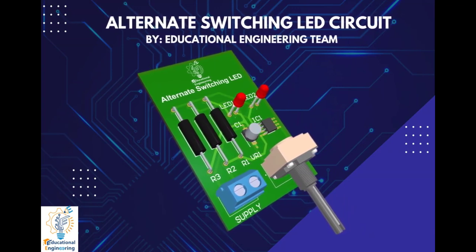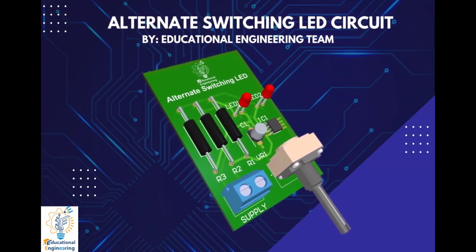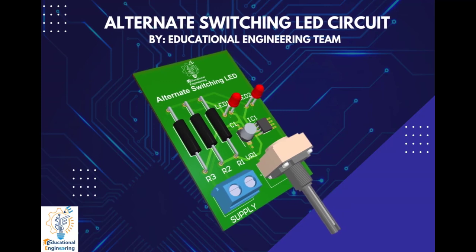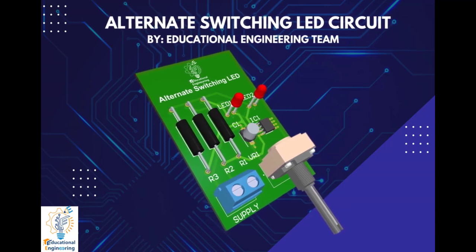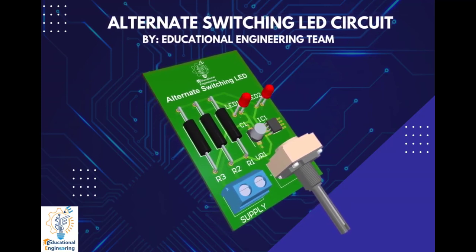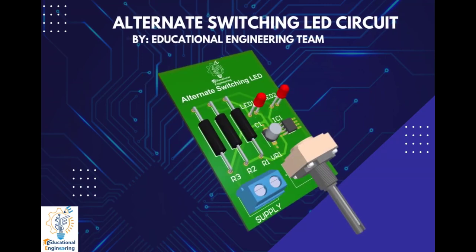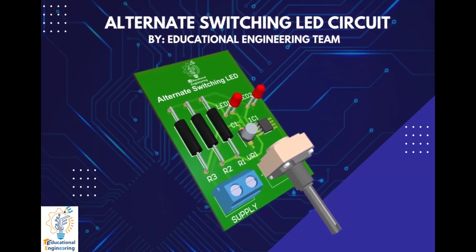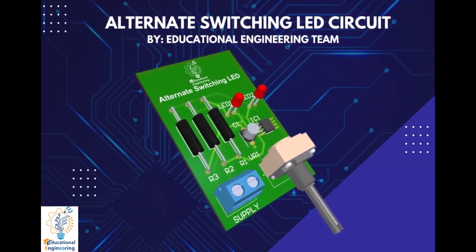When the output pulse goes low, LED 1 will be grounded to pin 3 of the 555 IC. Since the IC can sink currents up to 200 mA, LED 1 will be switched on for the duration of the low pulse output from the IC. Resistors should be used in order to prevent damage to the LEDs. Thus, the alternate switching of the LEDs gives a beautiful effect.